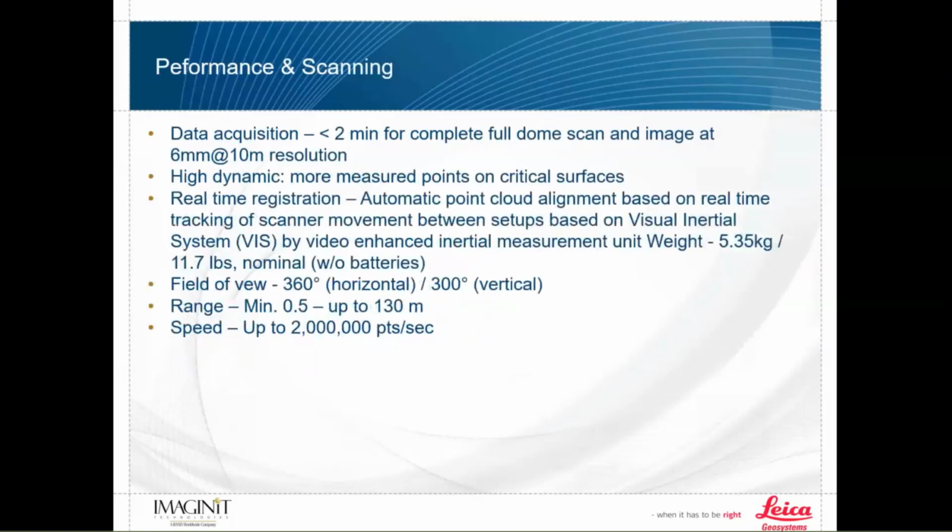Data acquisition, on a medium setting, we're talking less than 2 minutes. That's at about a 6 millimeter at 10 meter range. For those of us that want to do the quick math in our head, that's about 1/4 of an inch at 33 feet. The actual spec on that's about 1 minute and 51 seconds.